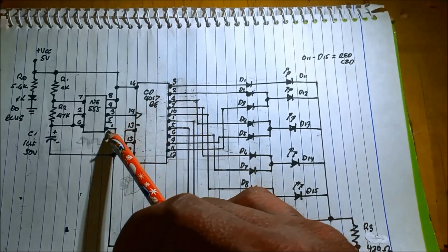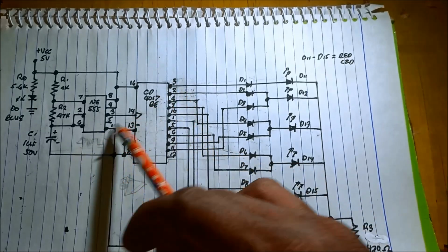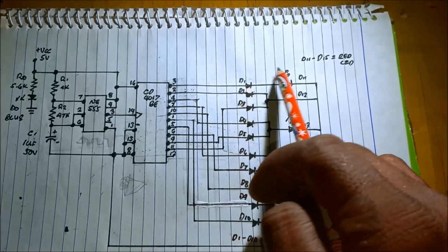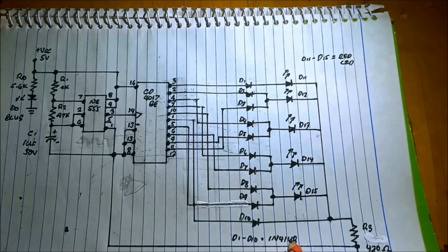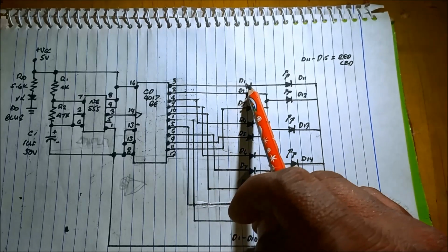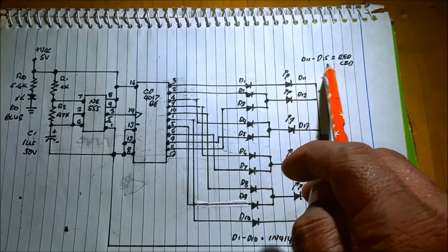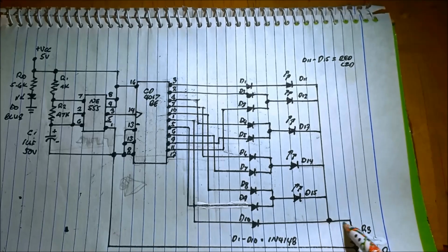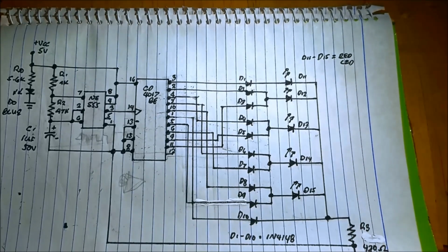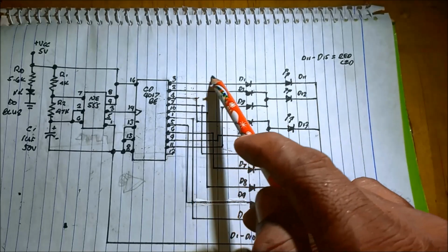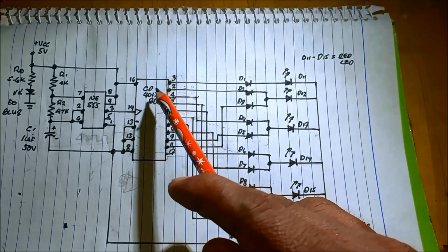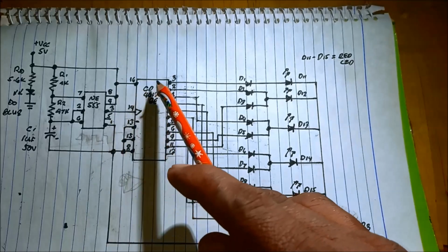When this one receives the first pulse, the current flows into the D1, which is the pass switching diode, turning on this LED, D11 red LED, and then connected all to the R3 470 ohms current limiting resistor. That is the first one to turn on. As I've said, this is a sequencer. The next pulse, it will toggle.